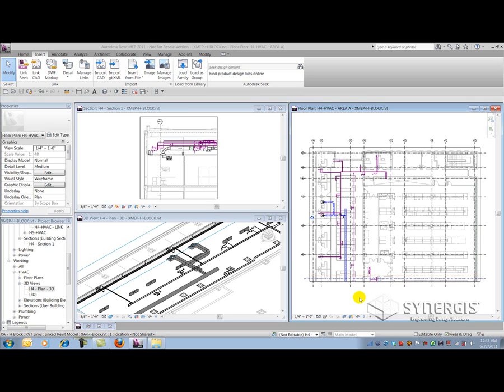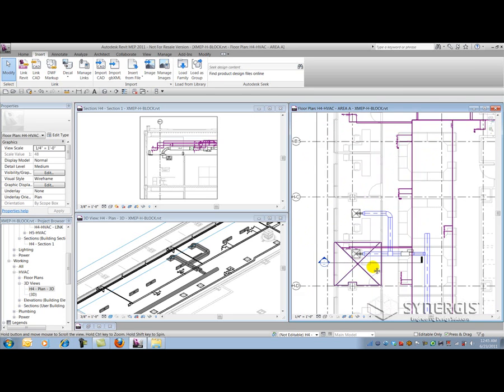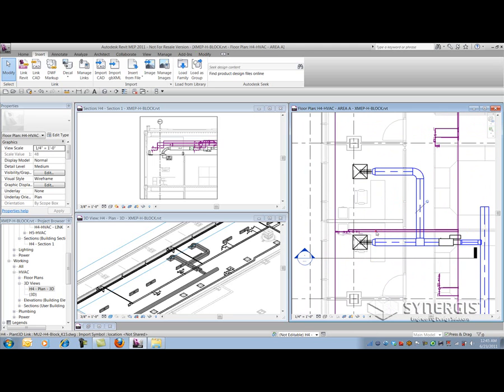The issue we're going to work on here is how the Plant 3D drawing file interacts with certain views in Revit. Now, this is not exclusive to Revit MEP. This would probably occur in Revit Architecture and Revit Structure. So, what I have here on the right side is a partial floor plan, or a dependent view of a floor plan, and we can see the AutoCAD Plant 3D drawing file linked in here. So if I just go into the area in question here, I'm going to select the linked drawing file.